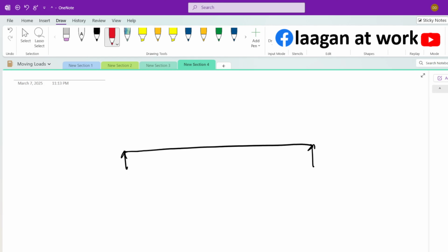If you position the biggest load at the midspan, I will just prove to you that what we calculated earlier was the maximum moment, where you position half of this resultant and the biggest load aligned with the center line of the beam.